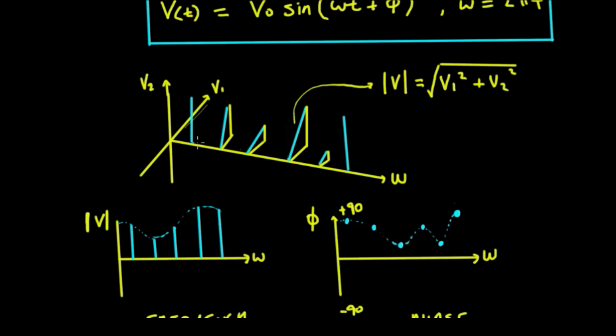But what we're interested in is not representing it in a 3-dimensional format here, because it gets difficult to try and draw out 3-dimensional drawings and obviously get information from those. So we want to represent it in a simpler format. Here's something that we could do. We could take all of these lengths of these phasors and turn them so that they sit along just this one axis. Okay, so that's what I've done here. I've just taken all these phasors and shifted them round so they sit up in this axis.